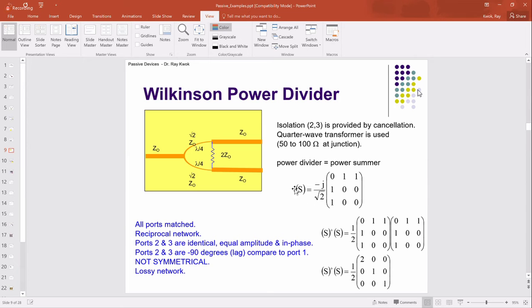So let's look at the S parameters. Here, if you see it, you know this is well matched. You know it's equal power splitting because these two are the same, right? You know they are in the same phase because they both are +1 and there's no j in here. I mean, the j is outside, right? This is the ideal power divider circuit you want, and this will provide that.